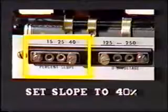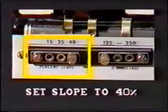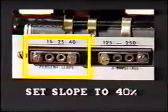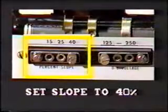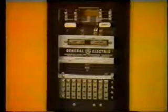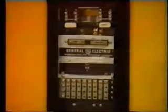So in order to allow high-speed tripping and avoid misoperation during the first few cycles of the fault, we would need to set the percentage differential to about 40%. Multi-restraint bus differential relays are available with up to 6 restraint circuits. The relay is quite fast-acting.